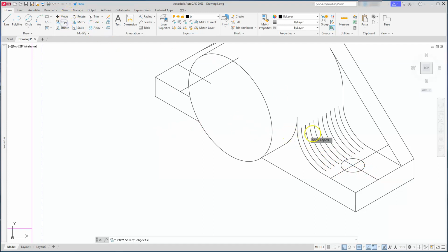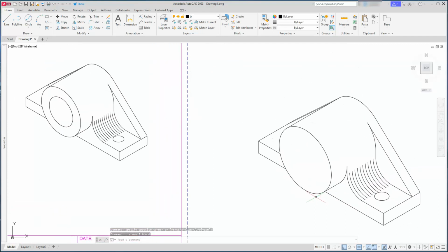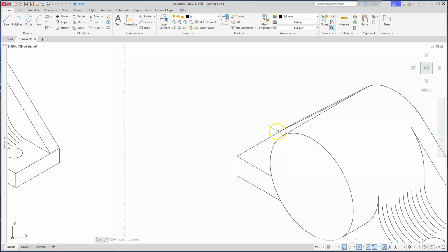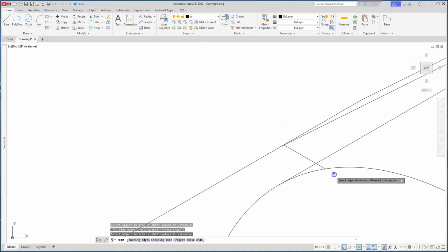Let's go ahead and copy this circle from this endpoint over to that intersection. So you will not even see that circle at all. So I can delete all of that stuff. And I can delete that. Alright, one last step I need to do is I'm just going to switch. Well, 2 more steps. I see that I also got rid of another line here. Let's draw a line from that intersection or endpoint going this direction. And we're going to come back and trim that portion off.